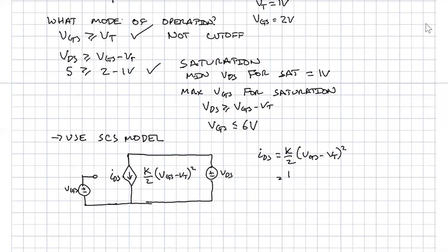I think we went through that unit analysis, but keep track of them. Always a good idea to make sure your units are right, because if your units aren't right, your answer won't be either. So VGS is 2 volts, VT is 1 volt. We square 1 and we still get 1, and so IDS is equal to 0.5 milliamp. And again, that's where the units are important, because K is not amps per volt, it's milliamps per volt.